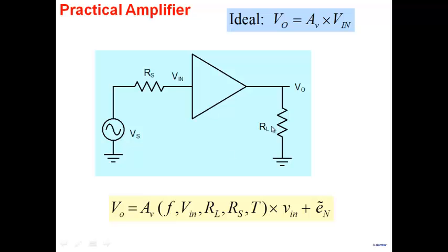Now, gain, which means that gain at a certain frequency is so much, and gain at a certain other frequency is something else. So that's a non-ideality. Ideally, I would expect my amplifier to have a constant gain. It should amplify all frequencies equally. If you imagine that the signal has, let's say, 2 frequencies, 1 kilohertz and 10 kilohertz. If the gain at 1 kilohertz is 100, and if the gain at 10 kilohertz is 75, what would happen to the output? Will it be an exact replica of the input?